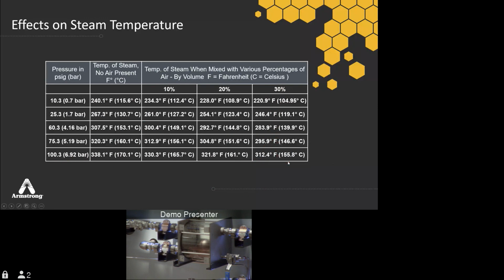And what's he likely to do? To increase the pressure, more than likely, because he's looking at his pressure gauge, not recognizing the temperature's not there. The solution for that is the use of a properly located thermostatic air vent.